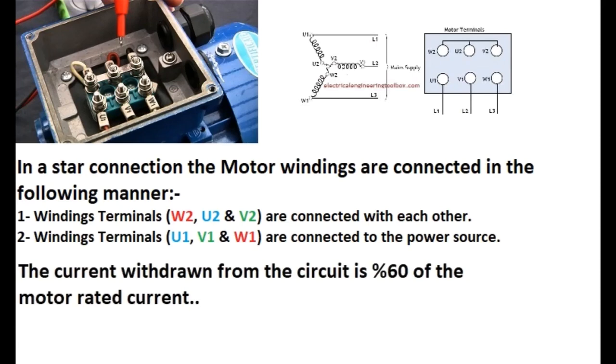full load. So it will give you the torque that is needed, but don't attach it as a Delta connection, because if you attach it with a Delta connection, it will withdraw the 400 volts while the AC motor is rated at 220 volts, so it will burn the windings. So the only way that you can attach it is with a star connection.